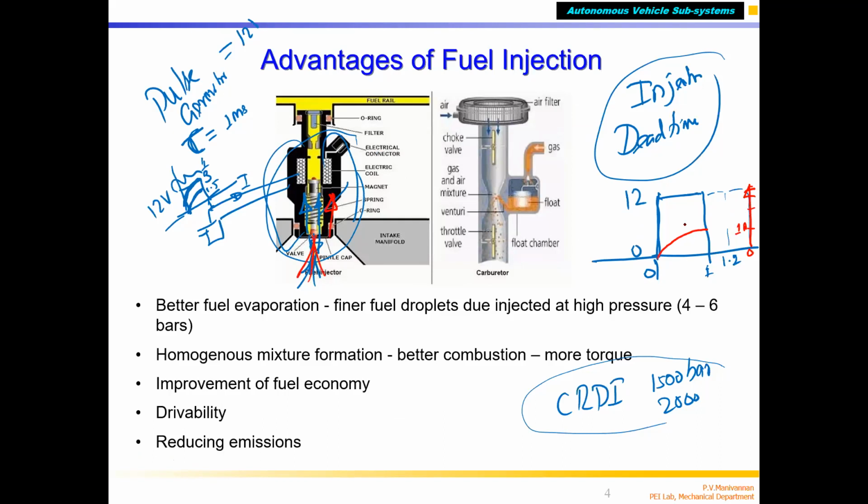How will you find out? As I told you, connect the fuel pump and injector, and give a pulse from the pulse generator. Then increase the pulse width. If the injector does not open at 1 millisecond, then give 1.2 millisecond or 1.4 millisecond. Give only one pulse, not continuous pulses, and watch the injector. If the injector opens, I know the current has reached the maximum injector current.